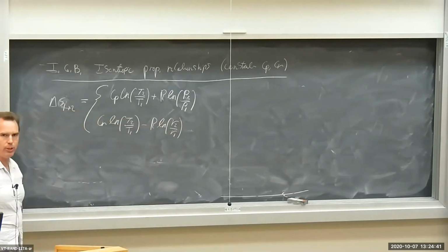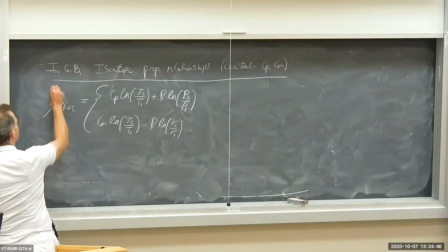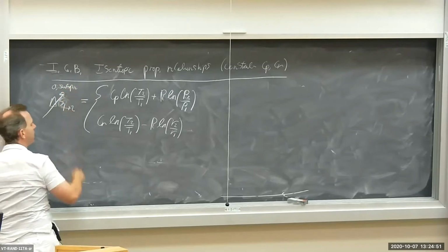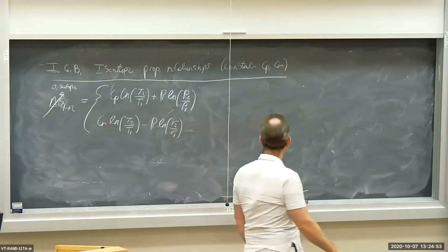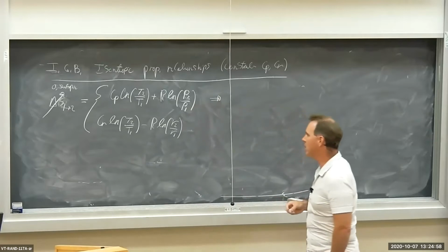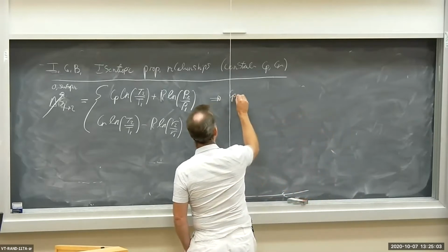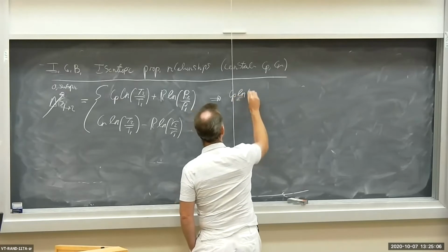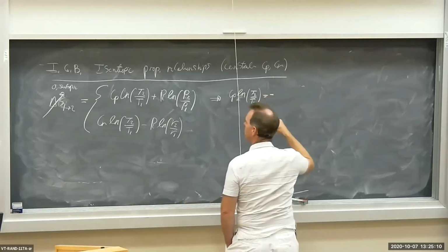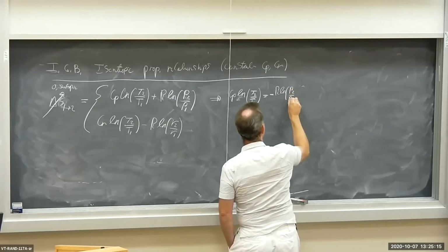So if delta S is equal to 0 for an isentropic process, then that implies, let's look at the first equation here, Cp ln T2 over T1 equals minus R ln P2 over P1.